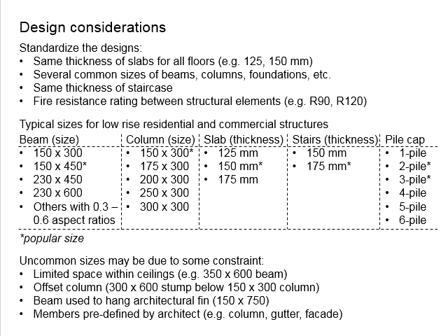Sometimes they need to plan their work ahead. For example, for the pouring concrete process, it is not as easy as we imagine. You ask for the ready-mix concrete to come. Now the concrete mixer comes ready, and you expect the concrete will be properly placed onto the structural element for the casting. This normally will not do. You need to plan the work path as well as the workflow together with the traffic for you to mobilize the concrete from the concrete mixer onto the structural element.